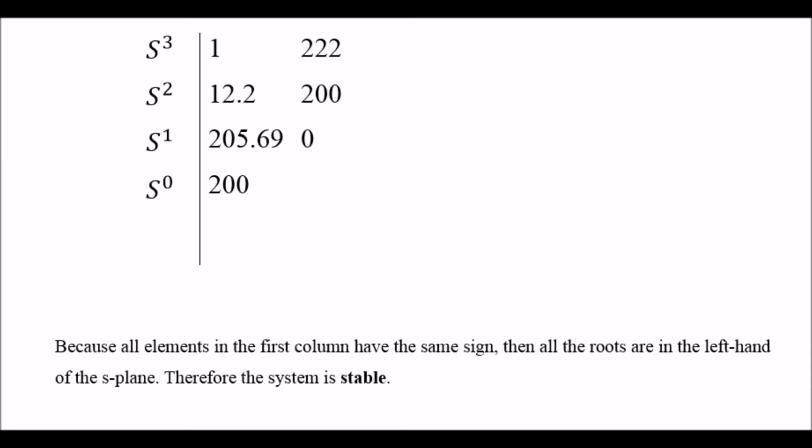After we get all the values, it shows that the first column has the same sign, and all the roots are in the left half of the S-plane. Therefore, the system is stable.